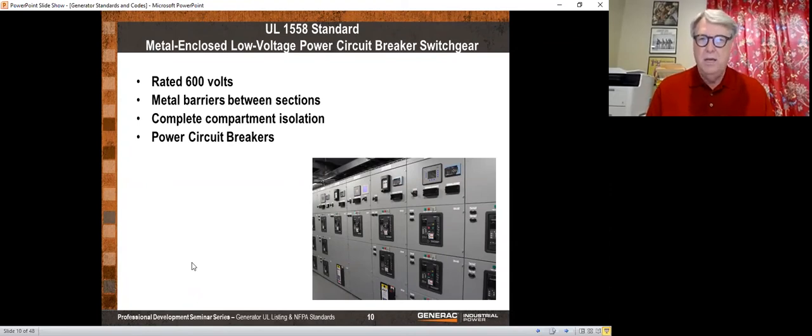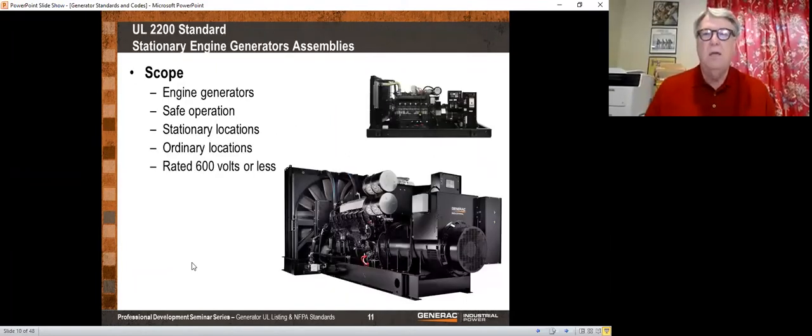I love these things. Again, this is just switchgear with a little more testosterone. Sometimes called metal frame circuit breakers. And they are used in heavy duty industrial installations. When I was the director of engineering for Geneva Steel, we always bought this type of switchgear because it was heavy duty, had high withstand ratings, and it could be maintained. Whereas an insulated case or molded case circuit breaker, you can't really maintain those. You're supposed to leave them sealed. So these are generally heavier duty in industrial installations.